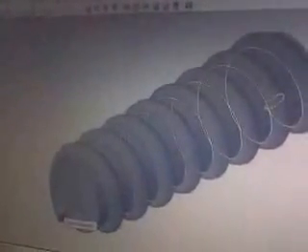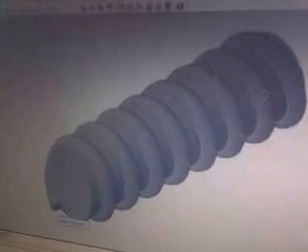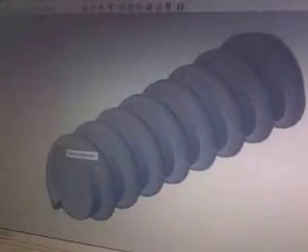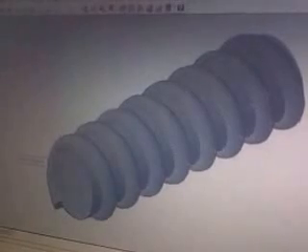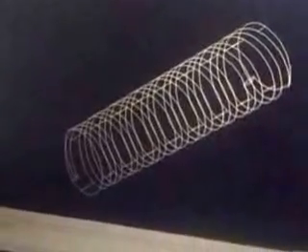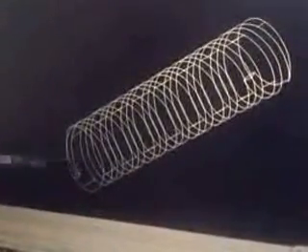Now that is exactly what I want, but you can actually do something for this by going to solid editing. You choose subtract. The object I want to subtract is the cylinder. Subtract it from this. Then I have this. Okay, now I go back to my 2D wireframe. You can see it has already formed the groove and the pitch is already there.